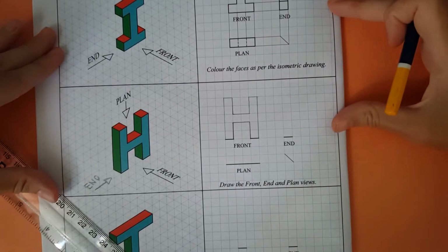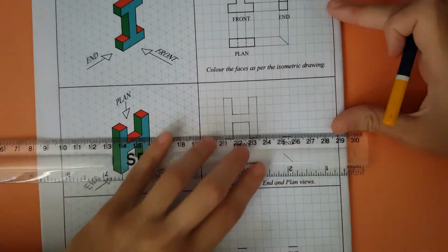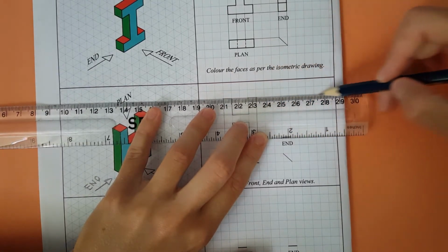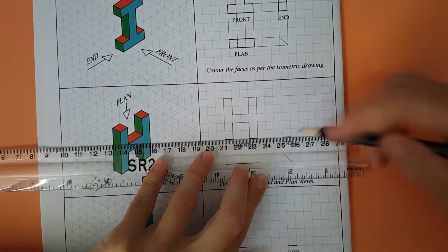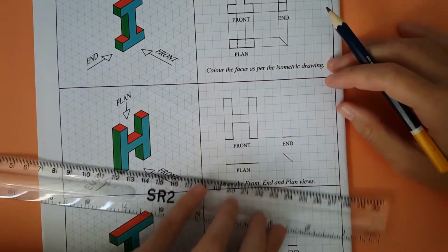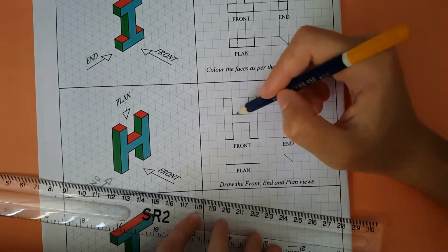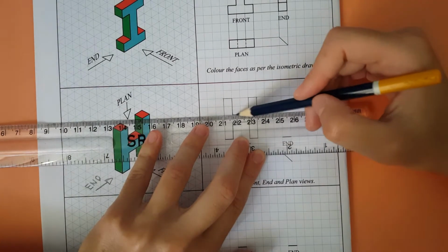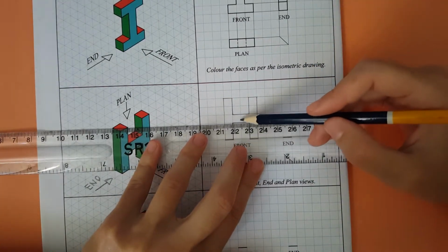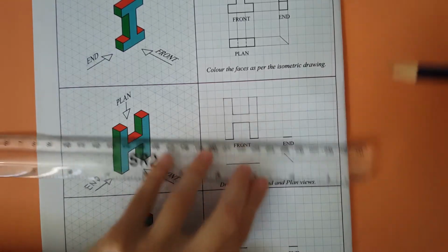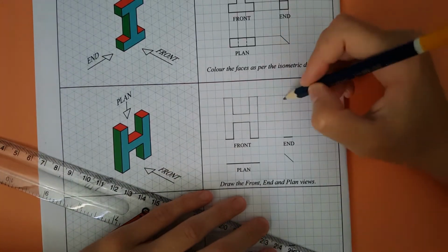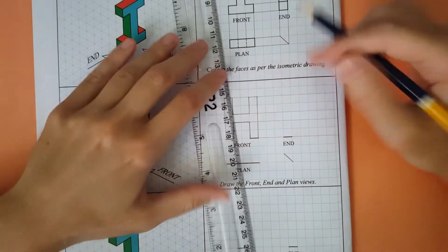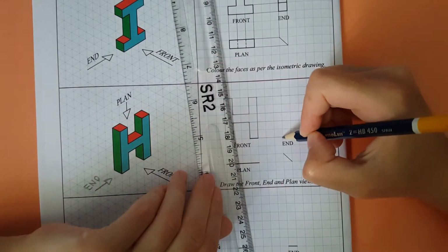Let's continue to our example. And let's project each horizontal line that we see on the front elevation onto our end. And here I am also going to project these 2 midlines here onto our end, even though they're not going to be visible in our end elevation. So let's continue by drawing these vertical lines over here and then the top horizontal line.